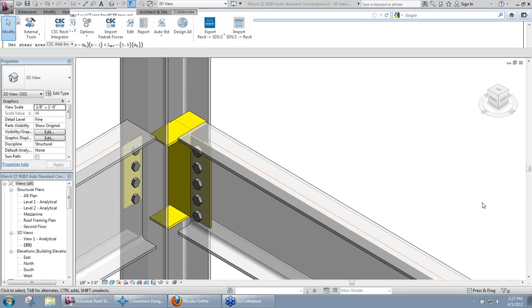Another question we have here is, can a bolt quantity be calculated using Revit? This is something, honestly, that keeps coming up quite a bit. It's a pretty popular question here. Currently, the way that we have this set up, it's pretty difficult to get and actually it's really not usable to get a bolt quantity or like a total bolt quantity calculated out of Revit. It is something that I think we're looking at here to make a few changes, possibly add a couple things so that people can get bolt quantities and whatnot out of it. So.